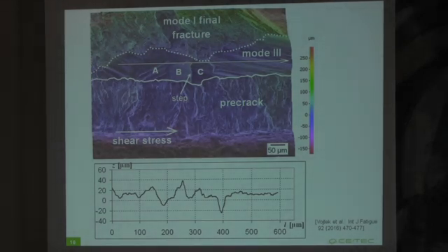And here is an example of fracture surface from the SEM in this central area. This is the crack propagation under a remote mode 3 loading. And we can see here also the lines we saw at the previous image, but they are highly inclined with respect to the pre-crack front. And it shows that actually the mode 3 loaded crack propagates locally in the direction of these fibrous patterns.